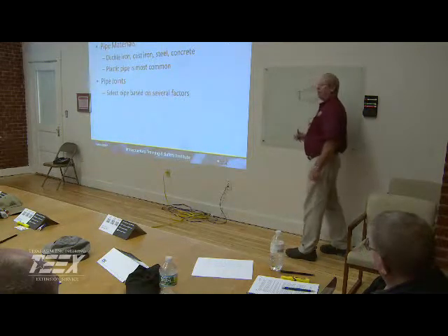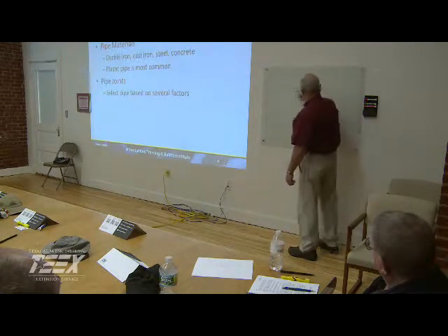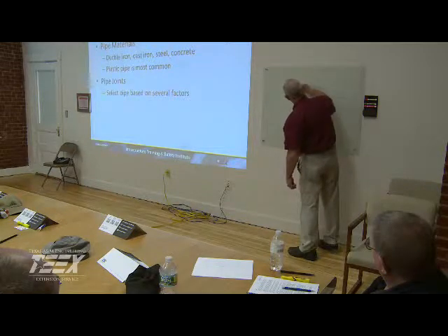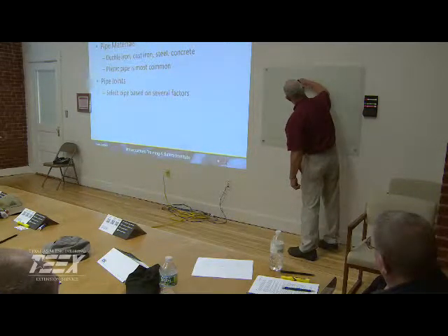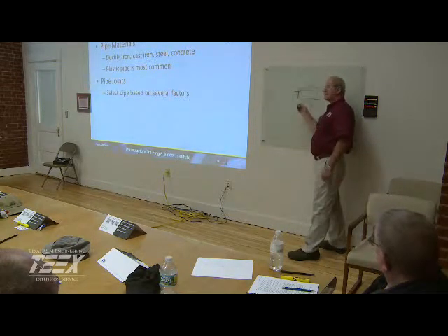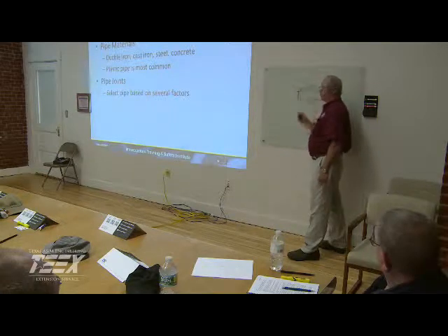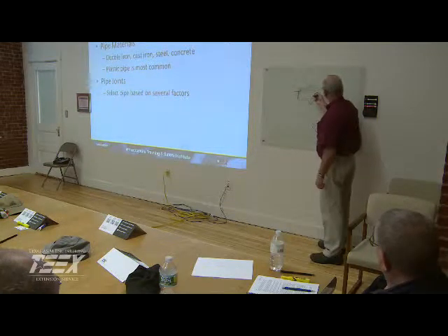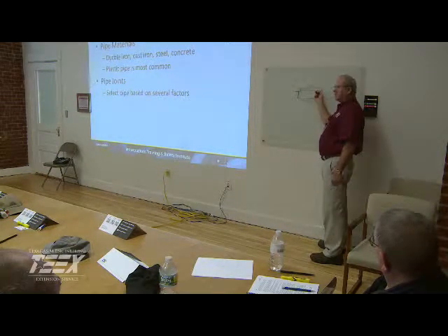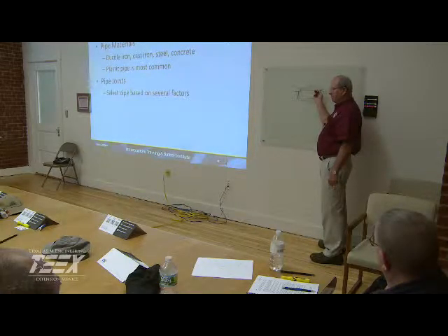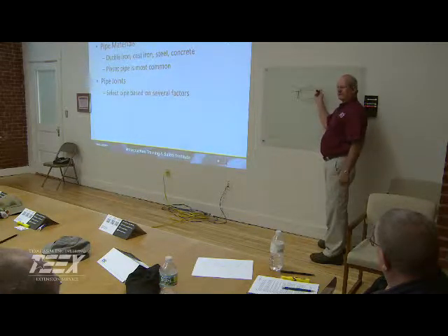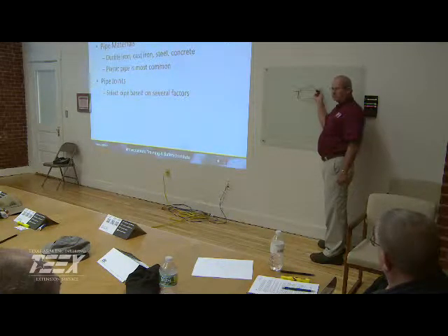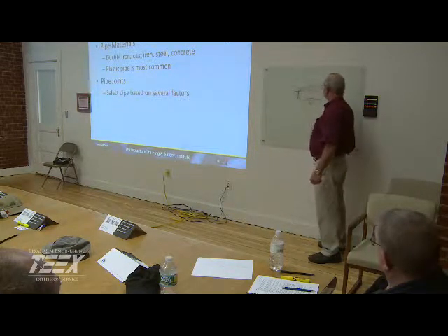That is a warning device. When you push this in, they say that you should never be any closer than up to 1 inch away. You never want to be past that. Okay, you want to maintain about 1 inch, because what happens, the end of the barrel will seat up against the back side of the PVC and possibly could crack it. Okay, make sense? All right, so that's the good old push on.